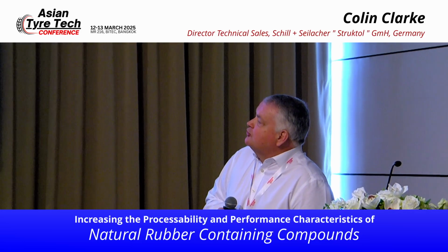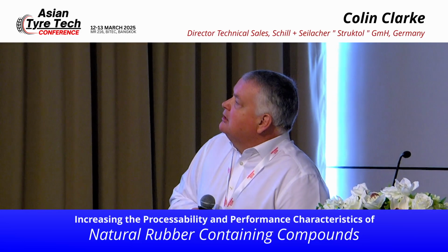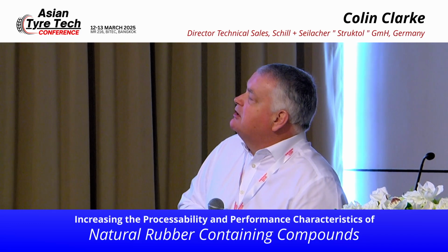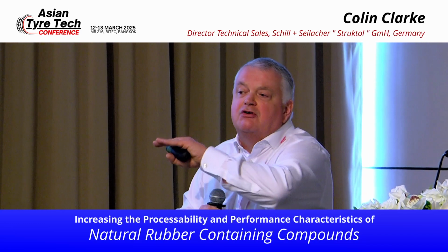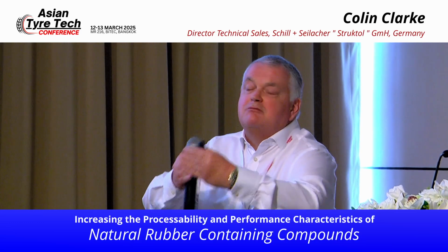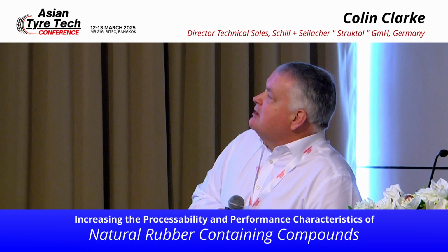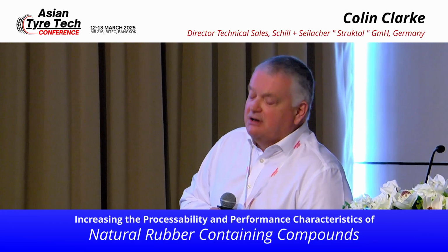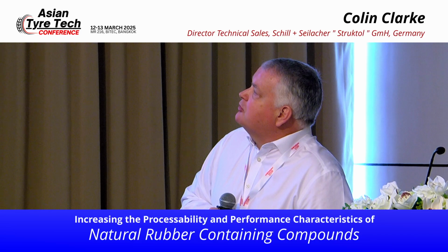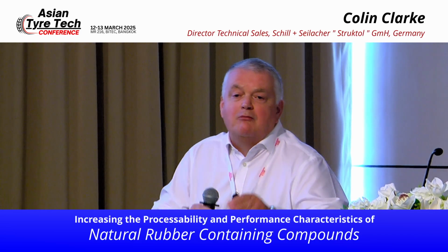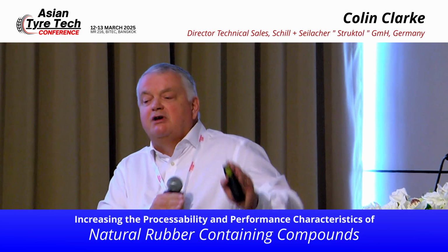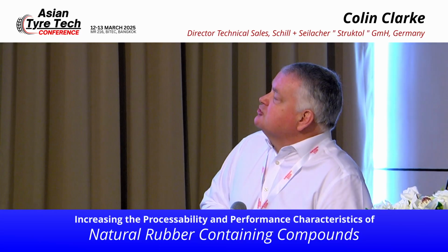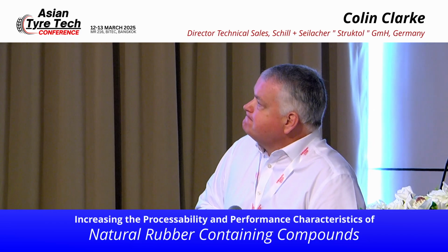If we look at the extrusion for the control and the three additives, of course, there are very minor increases in extruder output. The line speed hardly changes at all. We had a little bit of reduction in viscosity when we just extend the mixing without additive. Of course, chemical peptizer gives us a big improvement, with 50% more line speed. But actually, the new product really doubles that, because we have low Mooney viscosity and a lubricating action, we can really make the compound flow, and that's beneficial for our processing.